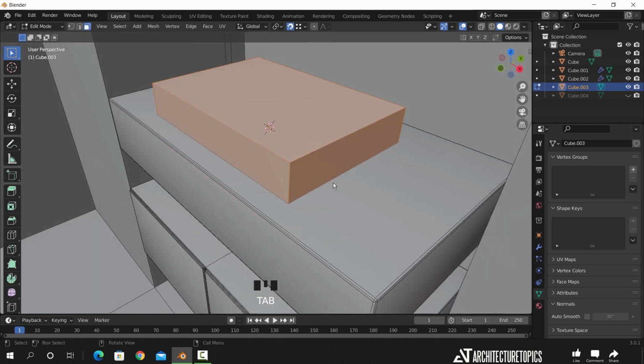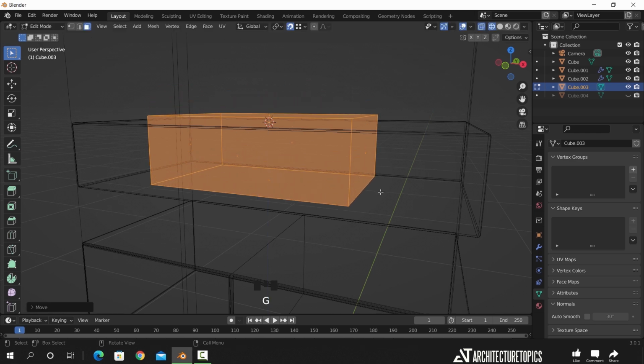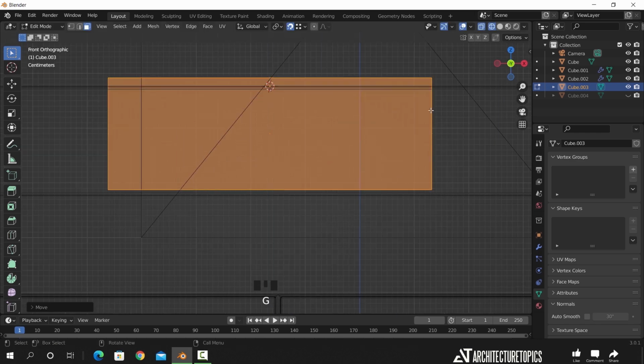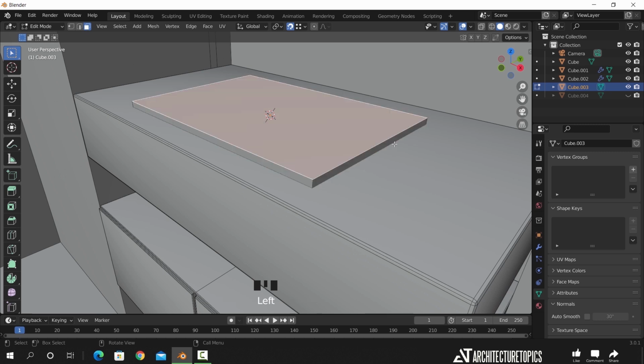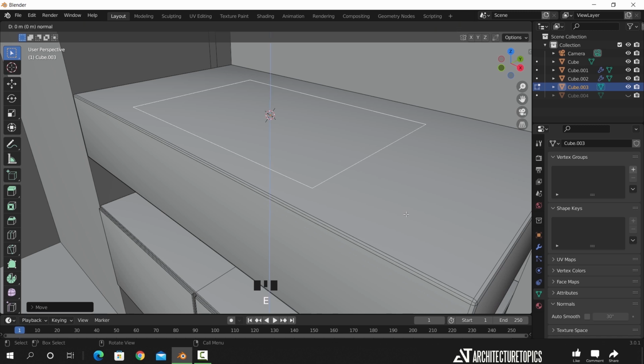Now with this one, we can move it down a bit, then with the top face, we need a small part to extrude along normals, so you can add a simple cut on it, or like me, I just move the face down a bit, then extrude it up.